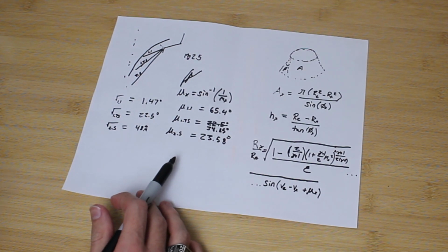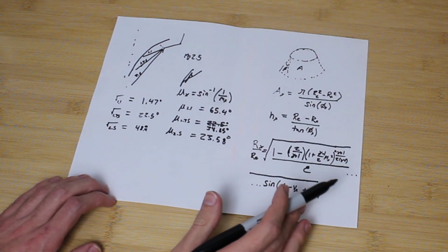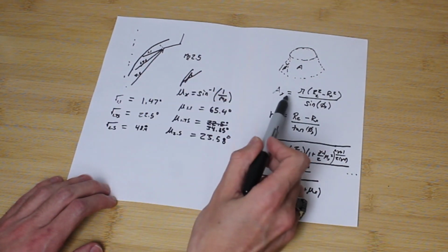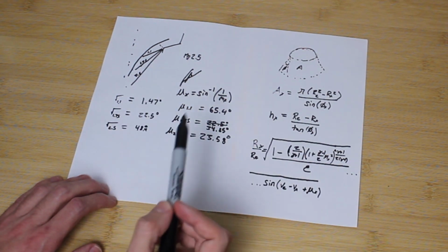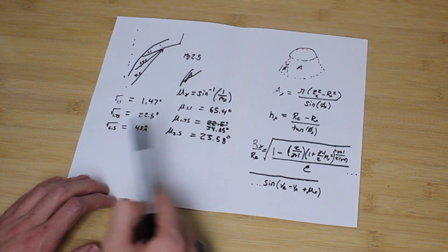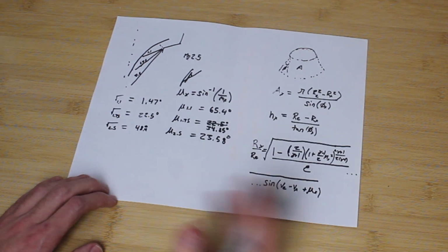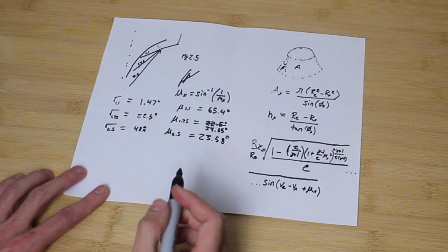So that right there is sufficient to define the entire geometry of the spike. And if you're curious what the gas properties are at any position along the spike, essentially you find the area of the frustum from this equation here, defined by a line going to it. That gives you a Mach number, and then you can throw that Mach number into the isentropic flow equations and solve for things like the temperature, the density, or the velocity. So really, that's all you need to do to design your aerospike.